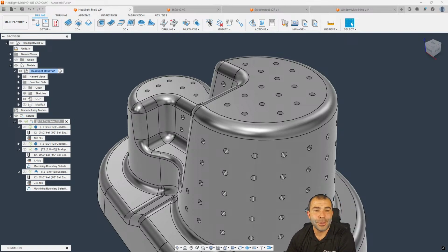So me personally, until Autodesk figures out how to do fixtures or a way to bring in my G code from an external file with the part and set it up on like a tombstone, I think the best way for me is I always do one part. I may model my entire assembly, but I would still do one part, multiple work offsets, and then that one part actually goes into my second, third, fourth setup. That way I can actually use continuous rest machining, right?